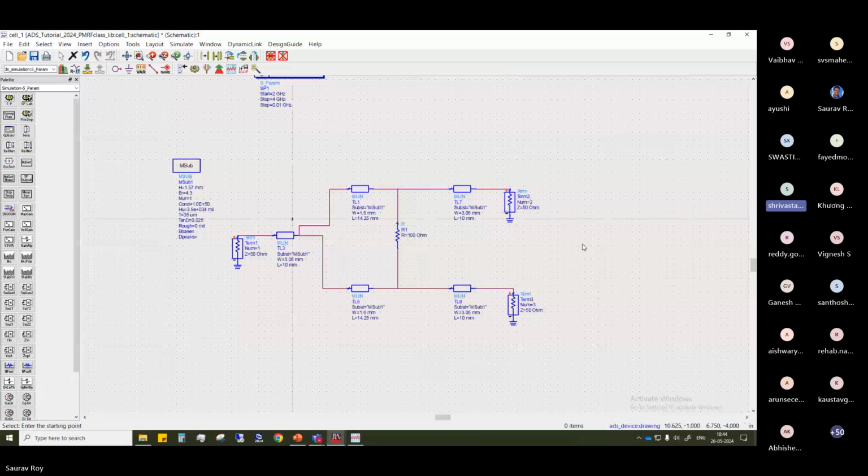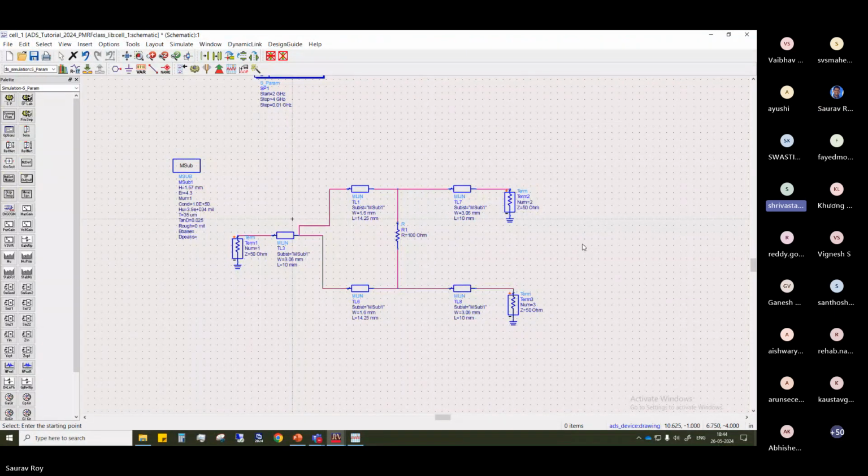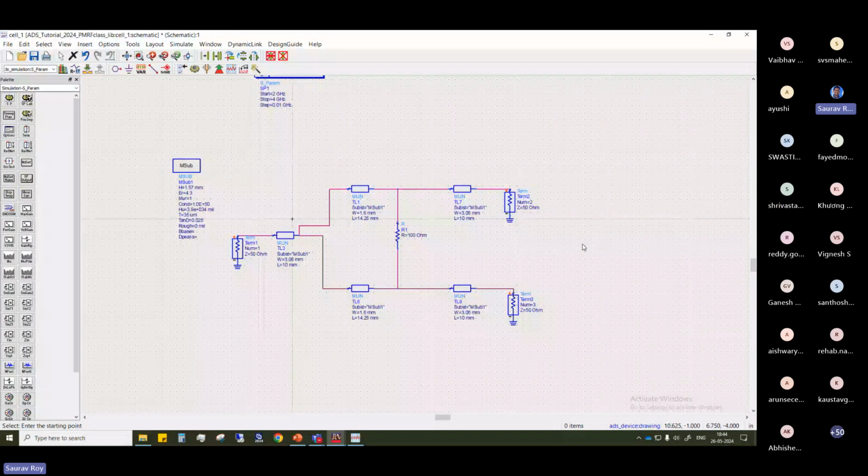So this is kind of a matching. When we are measuring S21, we terminate the other port, ensuring there is no reflection from the other ports. That is how S parameter is defined. That's why we are using this. Same thing from the hardware perspective also: if you fabricate a multi-port board, as I was telling somebody yesterday, if you have a 3-port board, you have to terminate the 3rd port if you want to take S21, because the definition tells the same thing here also. Okay, got it.